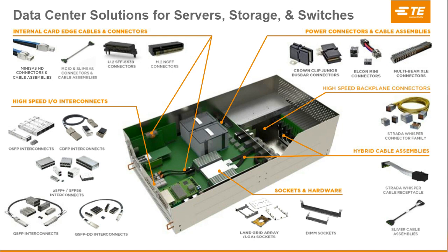As you're able to move faster, now you have to get essentially higher volume of data in a smaller space, and that's where data centers, particularly cloud data centers, are widely adopting the 8x112 QSFP-DD and OSFP form factors to get that increased I/O density, so that they're able to achieve 12 terabits in one rack unit.